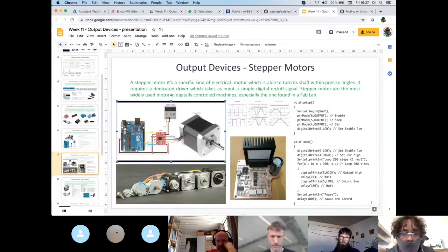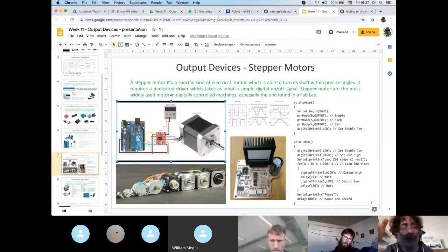So micro-stepping, guys, again, is useful to give you more resolution in the motors. Some motors can change behavior in a way that the more micro-stepping you have, the lower torque you have as output, the lower speed you can reach, depending on the motor. And also, for some motors, you cannot go over a certain amount of micro-stepping. So I remember with some NEMA 24, I tried 1/256 stepping, and this decay was not working at all, and the motor was just having super weird behavior.